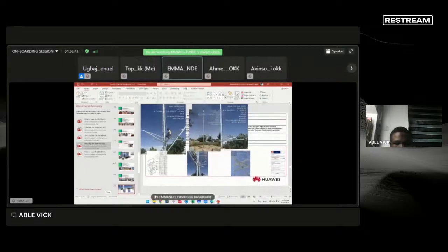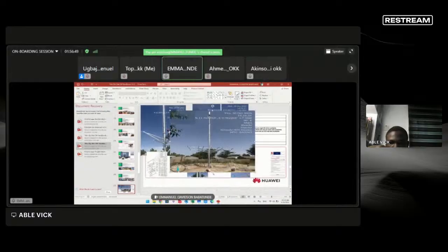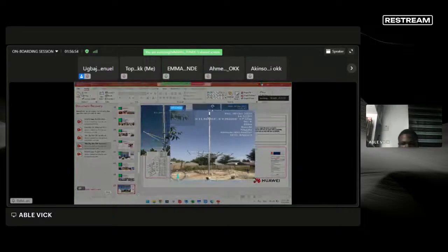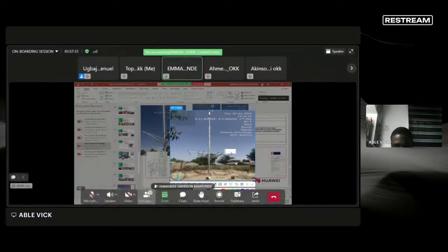When installing the sub-rail, you need to make sure of this part of the steel, this C channel. You can see this sub-rail has one part that enters inside like this. Can you see this face? This face on the sub-rail at the top has to face north. It's very, very important. This face has to face north.